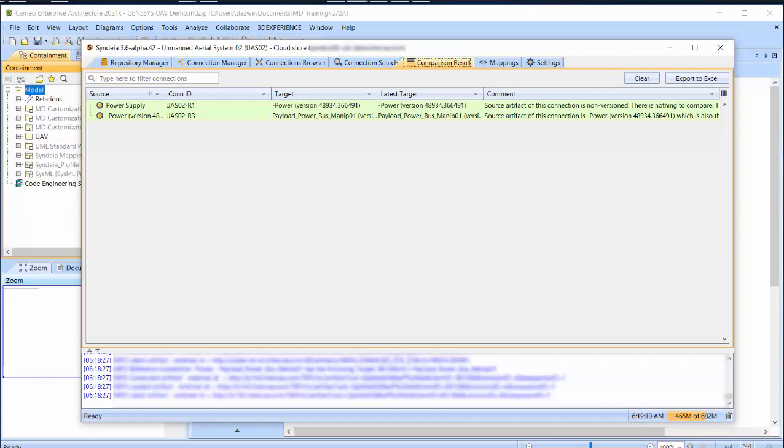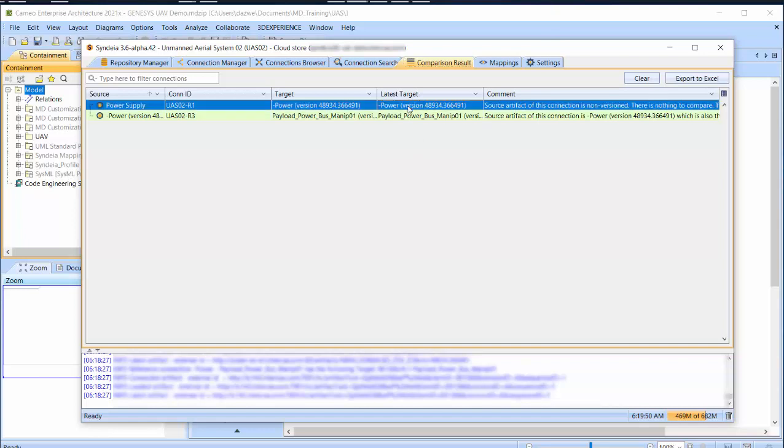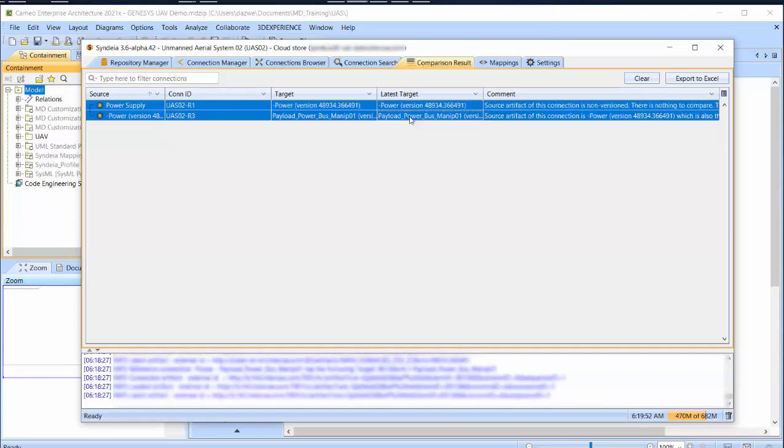Similarly, if only the version of the Team Center item revision had changed, then only that connection would turn red, because the connection was no longer pointing to the latest version of the Team Center item. I could choose any or all of the connections, and right-click either Sync Source to Target or Target to Source to update the connections to point to the latest version at both ends.